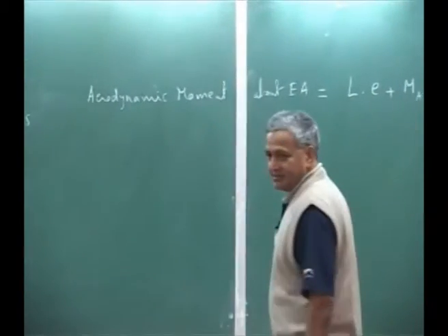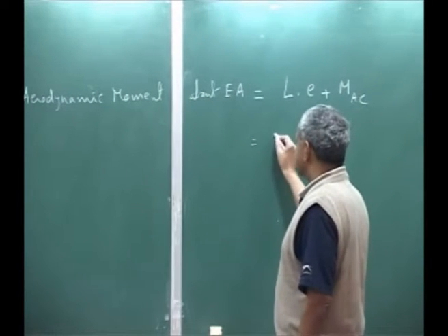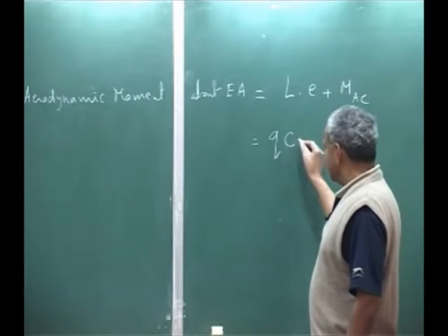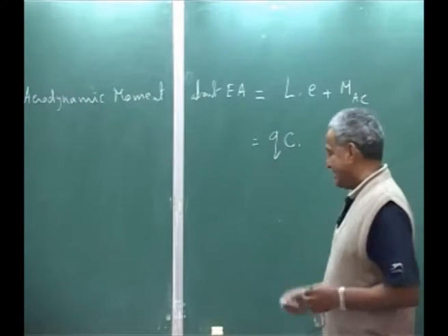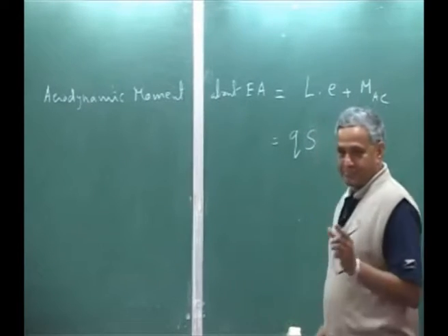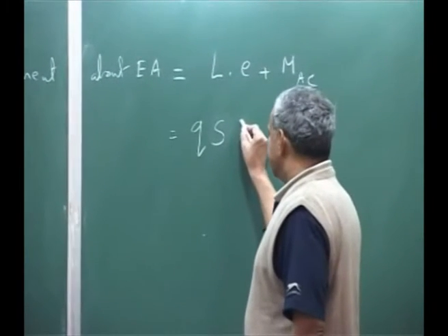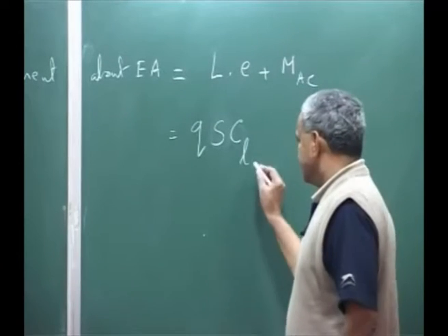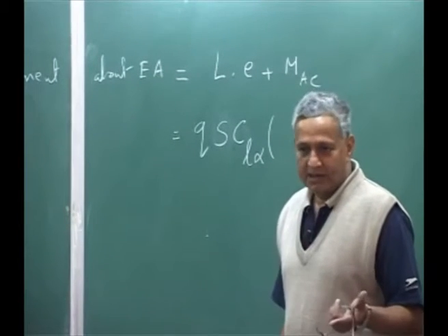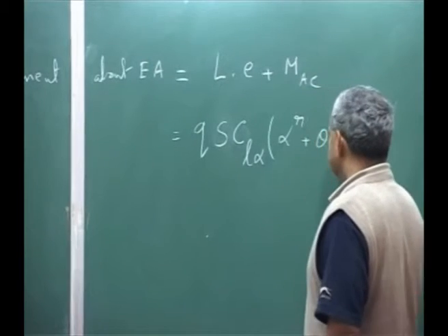Now the expression for lift, in subsonic, we will take it as all subsonic incompressible flow. So we can write it as, this is dynamic pressure into area which I take C into some depth. Instead you can always call it as C into the depth as the area. Okay. And then CL alpha. The lift coefficient, but we will write the lift coefficient as CL alpha times angle of attack, which is the effective angle of attack, which is alpha r plus theta into E.